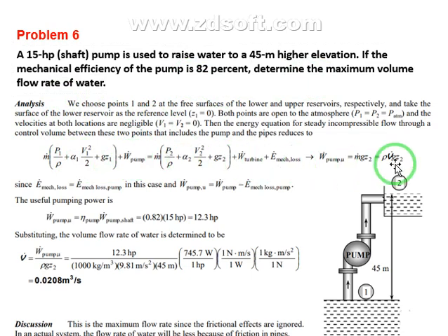We have this equation for the pump. We have W pump here, and g Z. This is the same equation as I did before in the previous example. So the first step is to get the net energy that we can get from the pump: efficiency 0.82 times 15, so it's 12.3 horsepower. That's what we need to get now. So we divide all this over rho g Z,